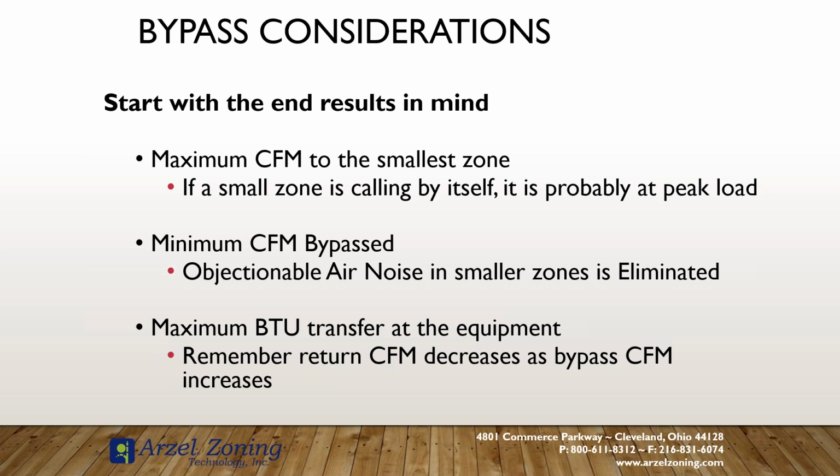So let's say my customer perception of airflow noise typically becomes a problem if I start to exceed 0.8, which is going to be my maximum for my blower performance data chart. I might start there at 0.8, let my customer listen to it. They say, yeah, it could be a little bit better. I'll take it back to 0.75. And then I let them listen to it.